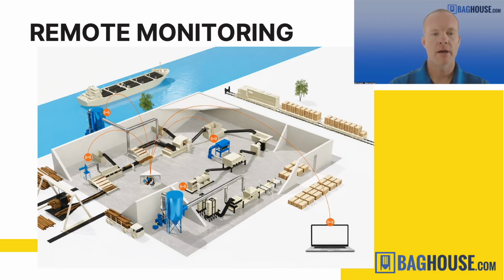Next slide is remote monitoring. So something that we offer now is systems for monitoring your system performance and the status of your equipment using connected sensors. Whereas the old school baghouse system just had a differential pressure gauge, you go out there, check the analog dial to see how things were doing, physical inspections and so forth. Now there are relatively low cost sensors that you can put in place for differential pressure, for airflow, for your fan bearings, all these kinds of things can be monitored remotely.